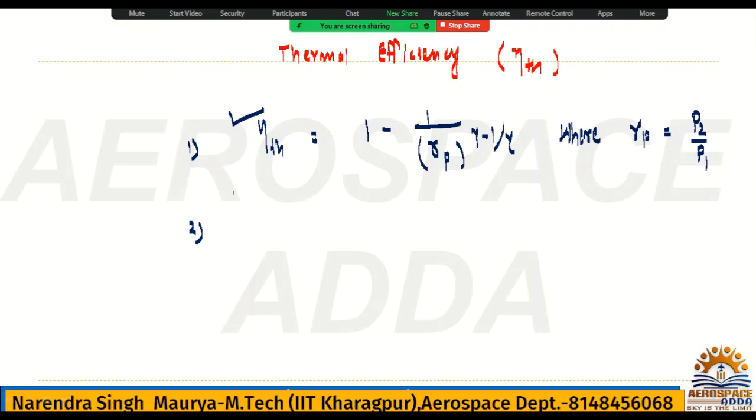So here the energy conversion is simply that the chemical energy of the fuel you inject into the combustion chamber, which is chemical, obviously has chemical energy. Once you start burning, that chemical energy will be converted into thermal energy, yes or no? That's the reason it is said thermal efficiency is the efficiency of energy conversion within the power plant itself. So it is considered an internal efficiency, while the propulsive efficiency resembles an external efficiency.